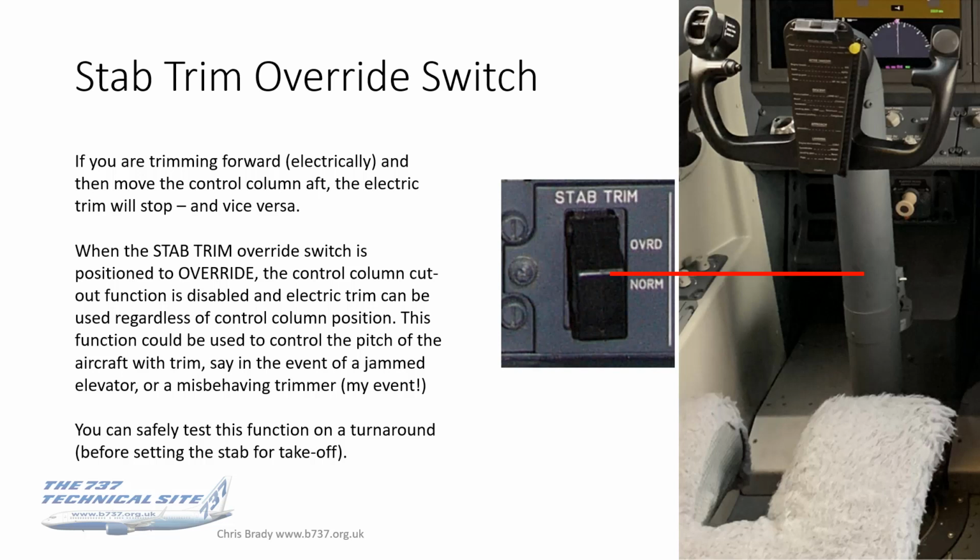So I took it back. And fortunately, I remembered this switch here. I moved the switch to override, and my stab trim was fully restored. I have to say that was the only time that ever happened to me in about 20 years of flying 737s. But there you go. It was a good one to have up your sleeve.